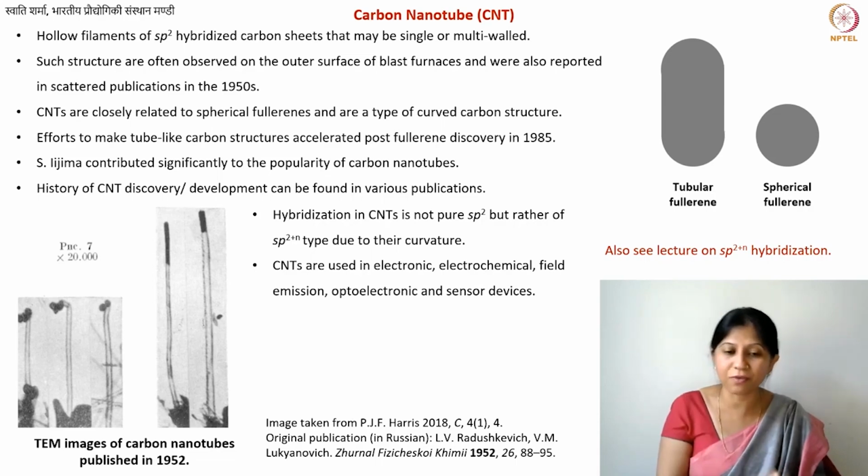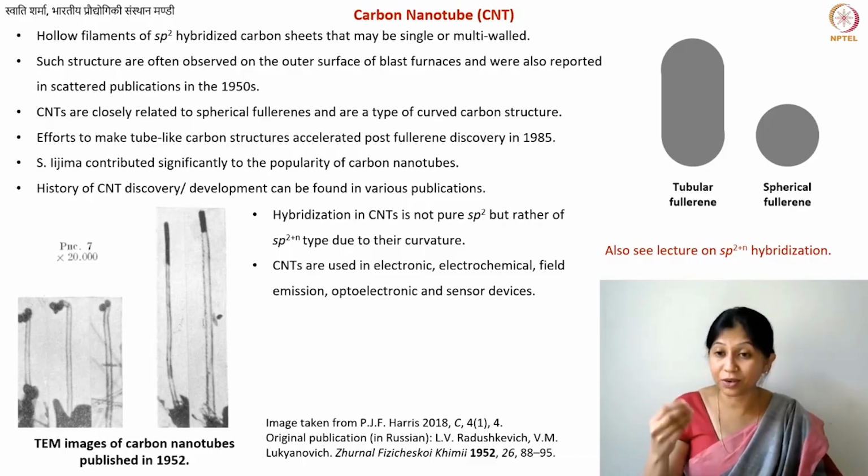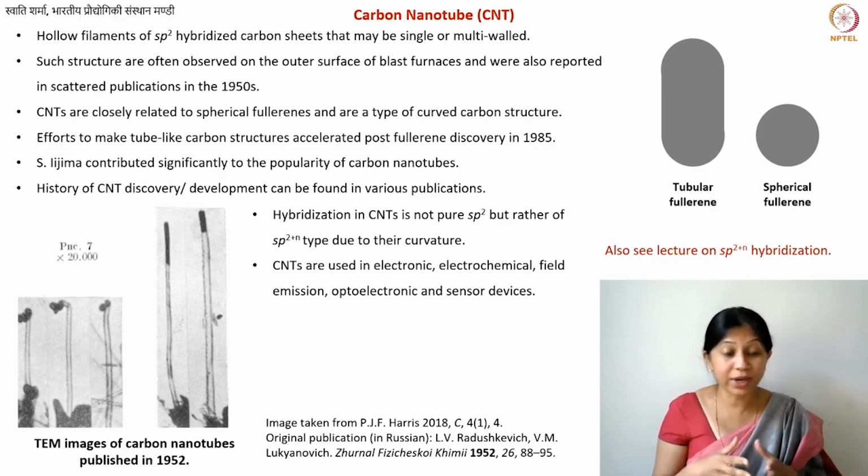Even in the case of carbon fibers, as we keep reducing the diameter of the fiber, at some point the defects cannot be there anymore, because that becomes a very high energy structure then. So that is why it has been predicted that carbon nanotubes have thousands of gigapascal, that is the Young's modulus.